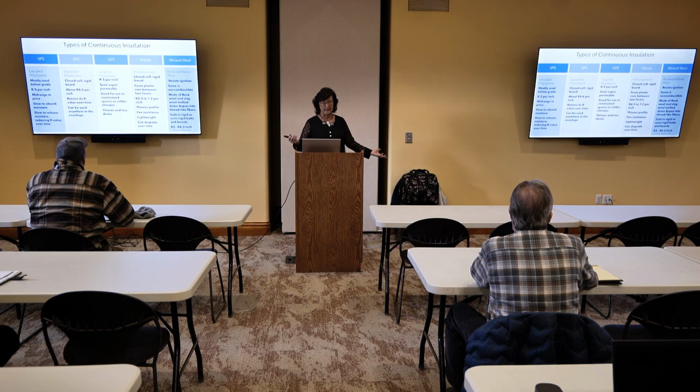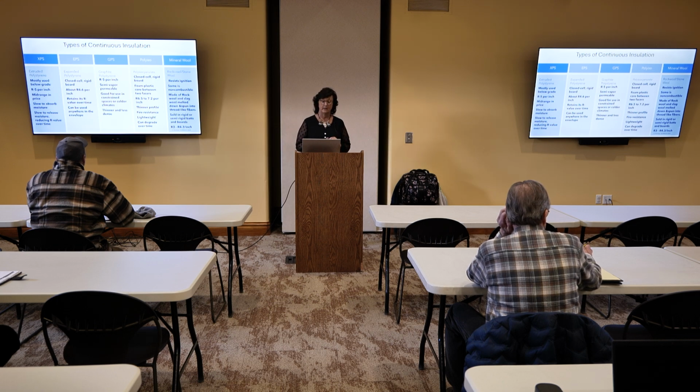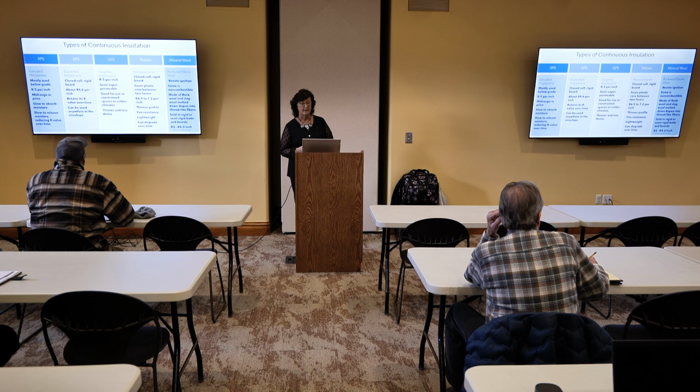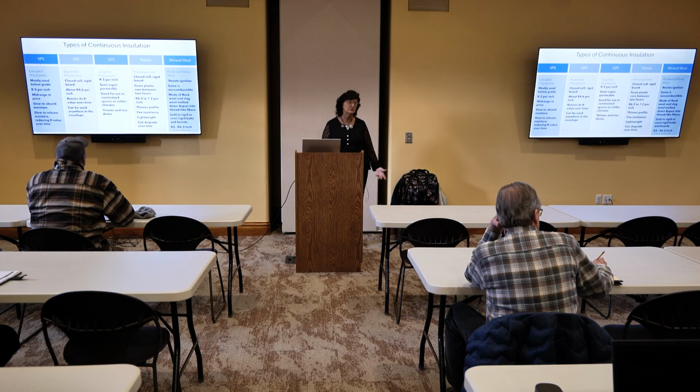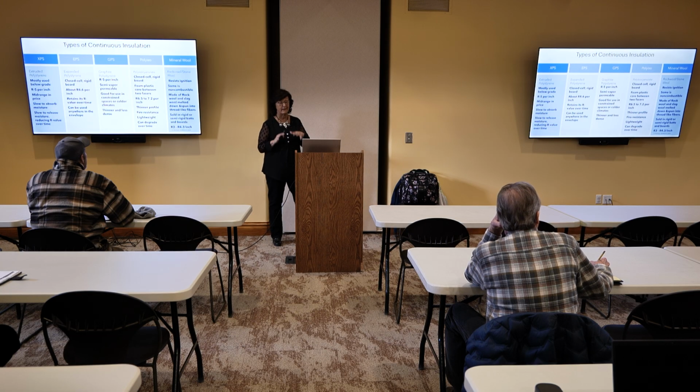And then mineral wool, right? That's like a rock wool. Pretty good. I think we're going to start seeing an increase in mineral wool with this wildfire resiliency code coming out at us, because there is some ignition resistance to it. Some of it is non-combustible, and so we're going to see that. It does have probably the lowest of all of them in U factors per inch, but the benefit of being able to use it for the wildfire code is probably going to outweigh that.